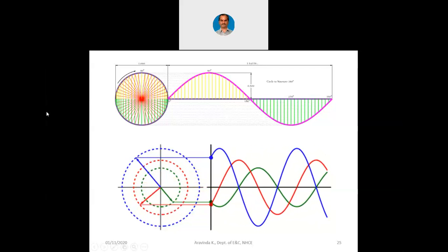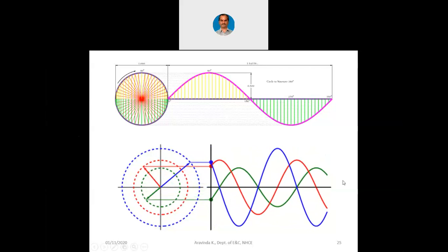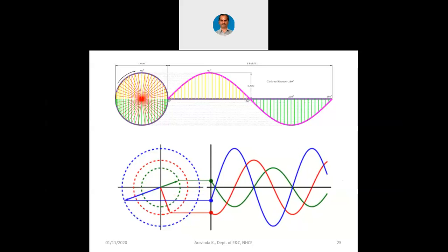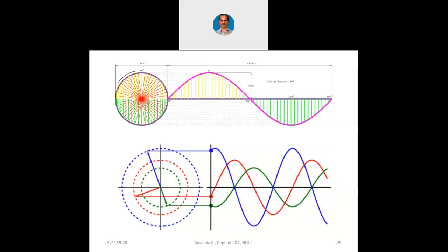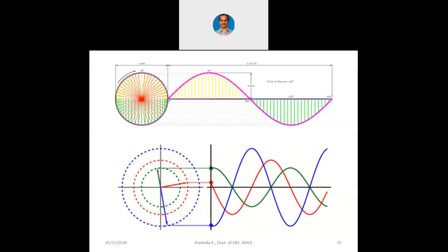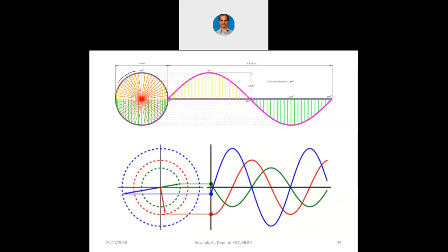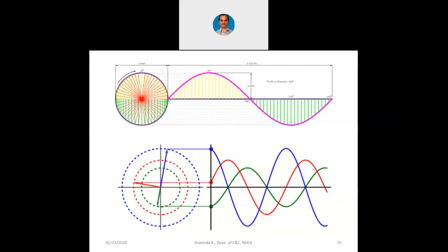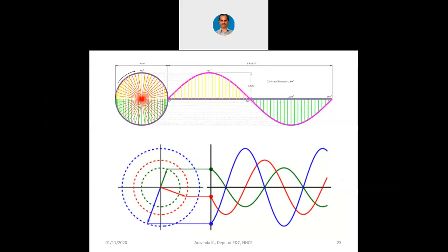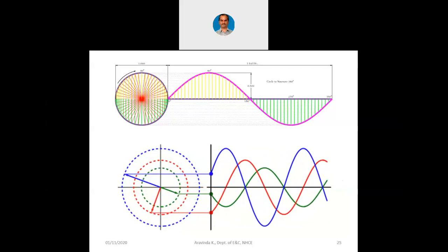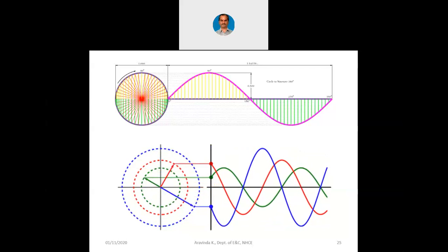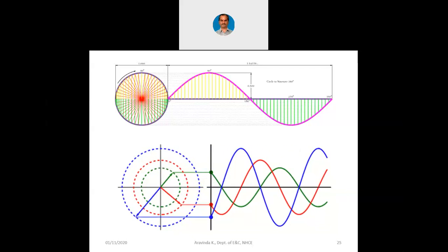Okay, in this way, I have just shown you a demonstration of how oscillators basically work. Oscillator means it is basically a cyclic movement. Now in electronics, the cyclic movement happens when we feed the output back to input and introduce a positive feedback. When we introduce a positive feedback, output comes back to input and it keeps on producing such cycles. That is the idea. So first remember, we are discussing oscillator as a primordial element.